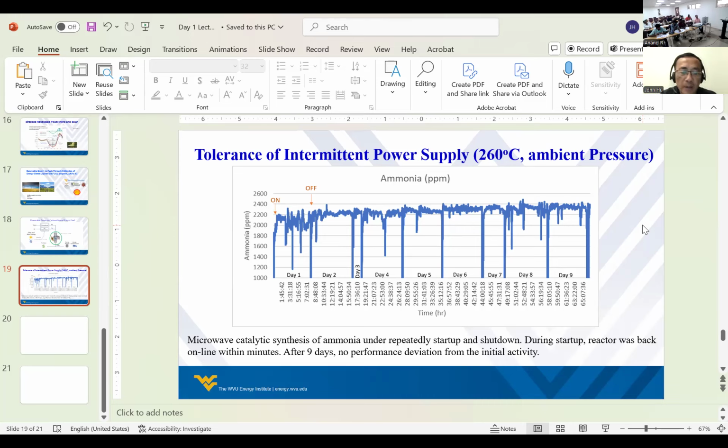So today, when you use a microwave, you don't have to go through the container. It's heating inside out. I'm going to repeat: microwave delivers energy onto the molecule, heating inside out. It's dielectric heating, not conductive heating. You follow me? So 260 degrees C gives you a wrong impression, but the actual reaction temperature is higher. So kinetics is faster, actually. You follow me? Did I answer your question?